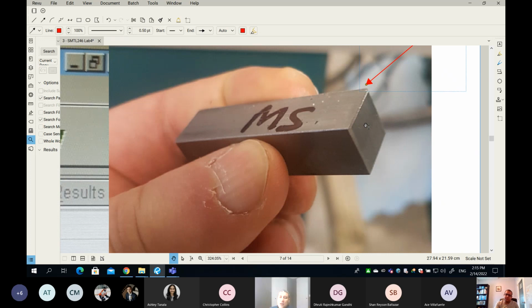No. No, exactly no, because if you remember the specimen that we use for tension, it has a profile, and the profile looks like we changed the diameter. Why? Because for tension, we need to grip on the head of the specimen. That's why it's a must, no choice. We need to make the specimen the way it looks for tension. For compression, we're not doing that.